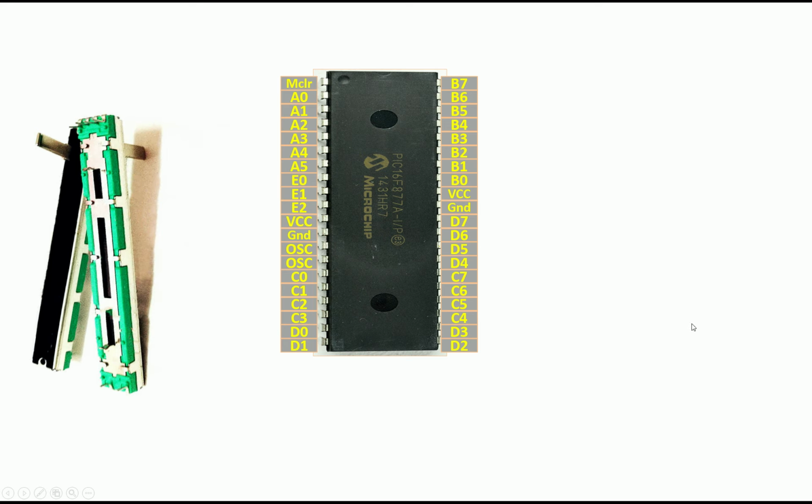Out of these 6 pins, only 3 will be used by our microcontroller. The rest of the 3 you can leave not connected. So the bottom right one, the top rightmost, and the second from the right if you hold it like this, these are the 3 pins we are going to use. The bottom right is the VCC, the extreme right on the top is the ground, and the second from the right on the top is the ADC pin.